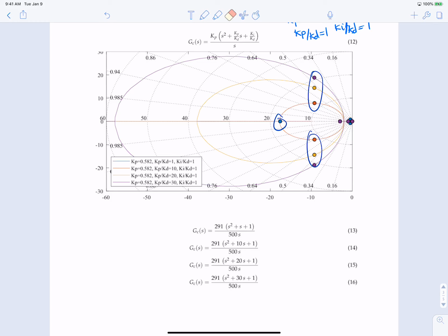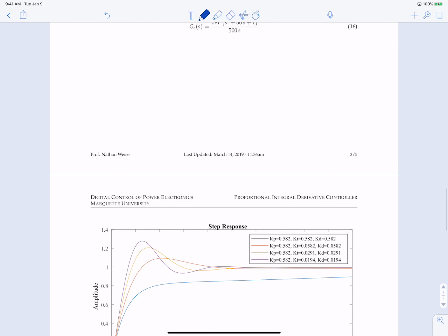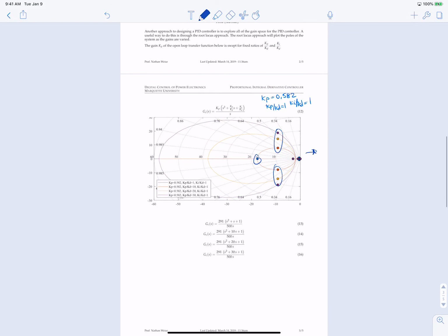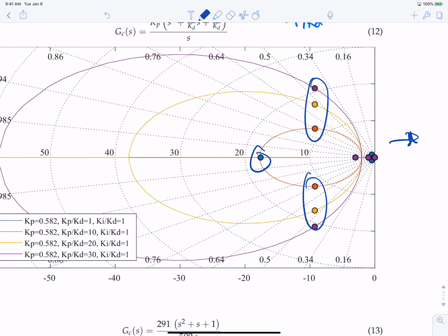The farther they are to the right near the imaginary axis, the slower the system is, which makes sense here. Actually, this is quite slow. Some of it comes up, about 80% of it, but then another one of the roots comes in and takes a really long time to respond. So you have this complex pair pole here, but you have this one. This one's going to dominate, but this one will go up right away.